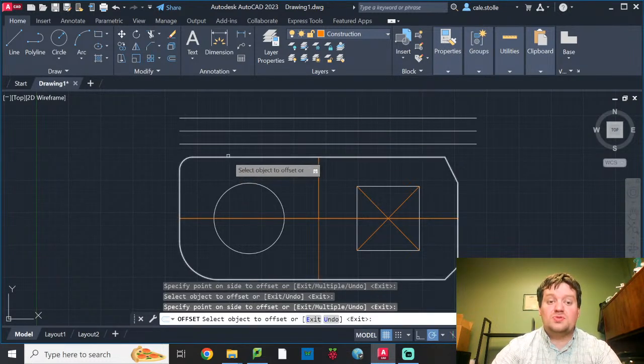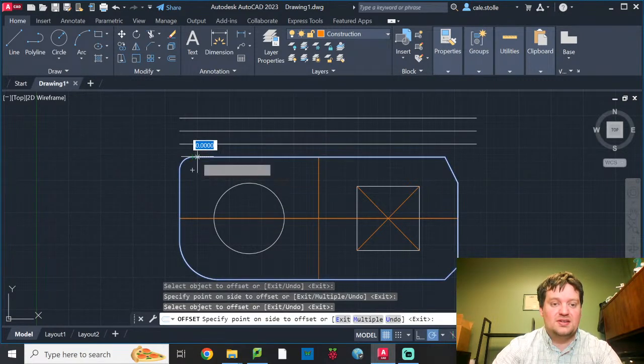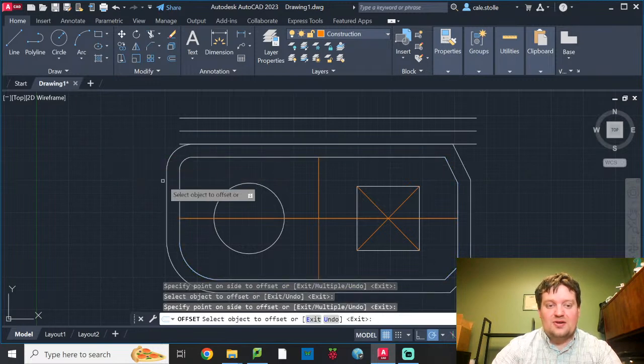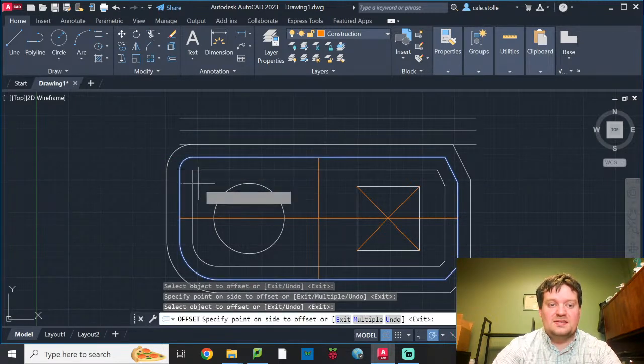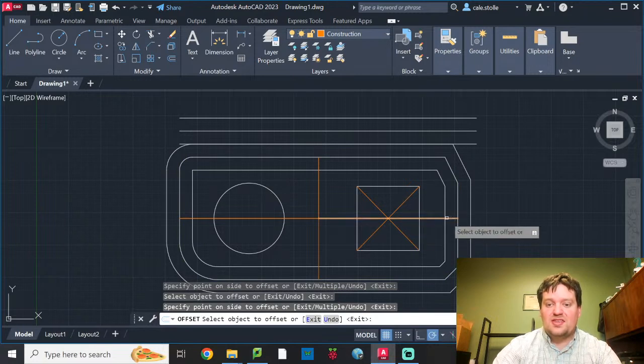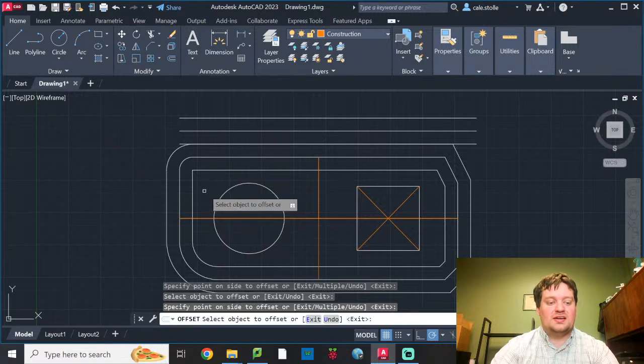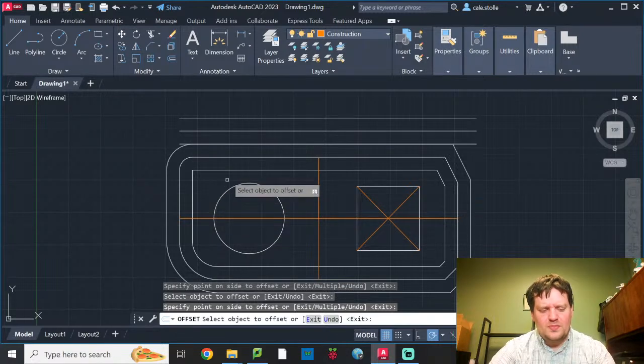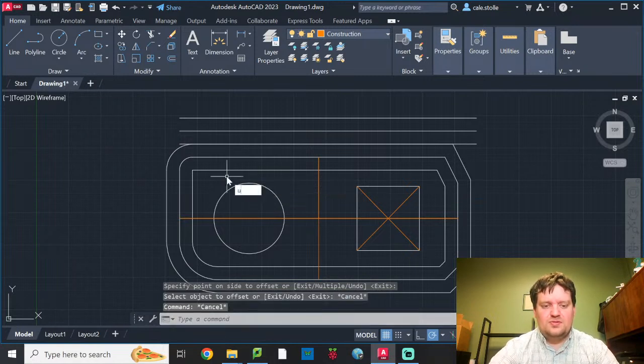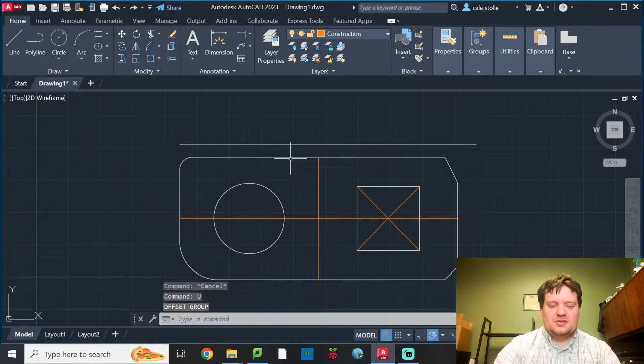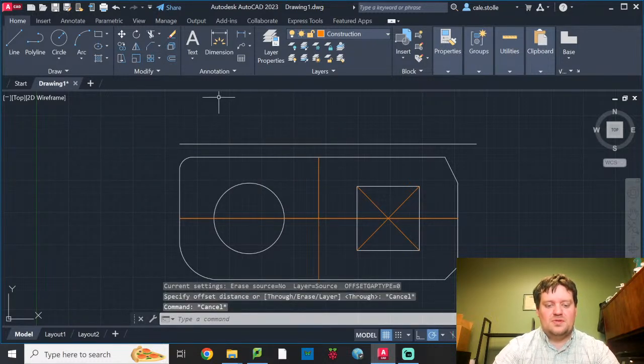But offset also works with polylines. As I said, this is a polyline because all of the lines are still connected. If I grab on this and click outward, you'll notice that all of the lines scale together. So here I've got all of them connected together. If these are all individual lines, say I'm going to go U and escape, U, enter. Okay, so here I'll go back and do my offset. Oh, no, escape. Don't do this part. I'm just showing you this for purpose.